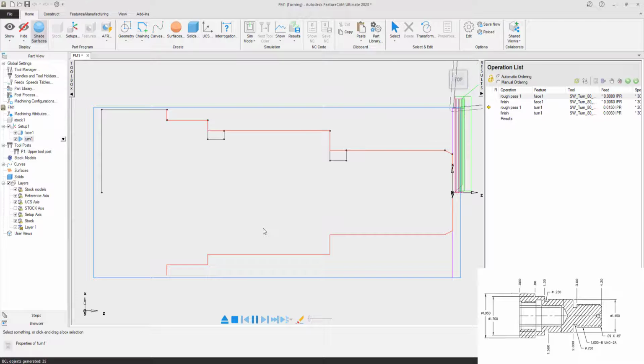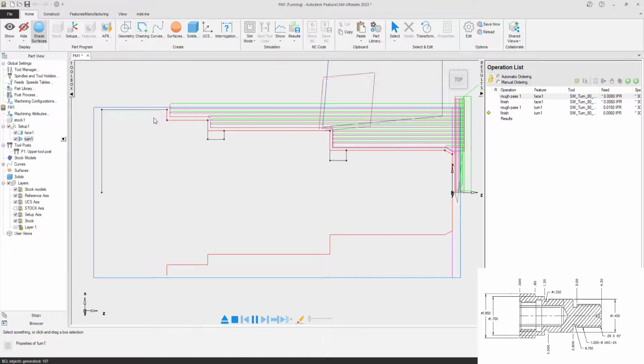So it's going to do my facing, and you can see it's doing my turning. Now remember, I have my chuck jaws holding onto this part, and they're sticking out 3/4 of an inch. So I only got this little bit hanging out of my chuck jaws. But I haven't turned this side yet, so that's kind of interesting. We're going to hit that in just a moment. So there's all my turn. Let's go back into 3D mode.